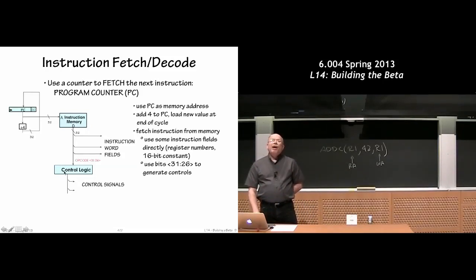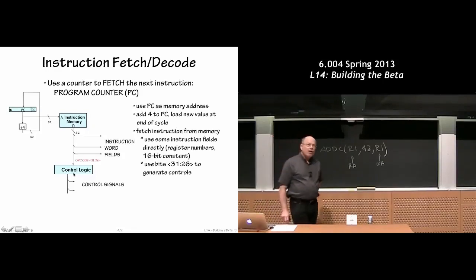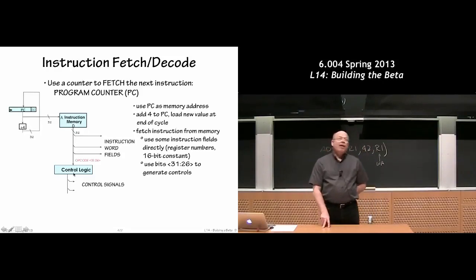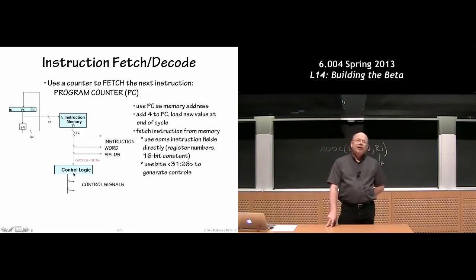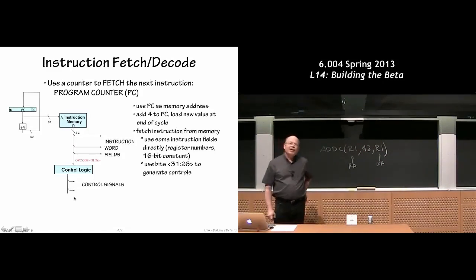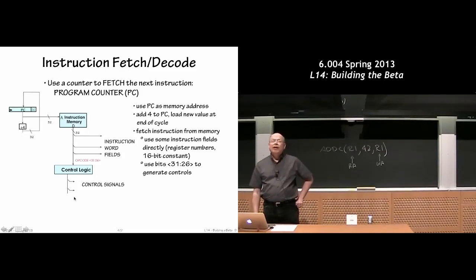However, we will take the opcode, the 6-bit opcode, and we're going to run it through this control logic, which is, think of it as just a big read-only memory. At least in this diagram, it would have 64 locations because we send in 6 bits. With 6 bits of information, there are 64 combinations. So depending on which of the 64 opcodes goes into here, we're going to develop a set of control signals. And that'll make more sense in just a second. As you start seeing what the control signals control, I hope all that will be clear.